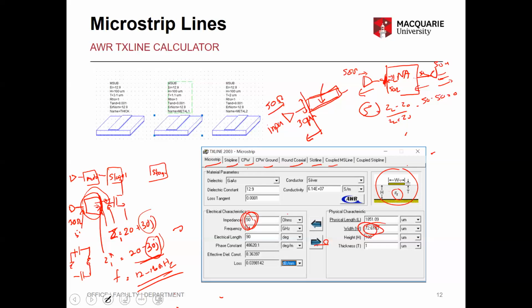So that's the outcome of this whole lecture. That's what we are trying to understand. If you know each parameter, you can work out the microstrip line impedances, and when you have a set of lumped elements, you can work out the impedance and then present the right impedance. So tune that so that it presents the right impedance to the input of the transistor.